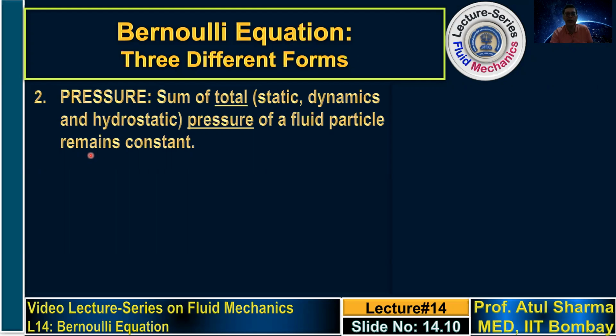So this rho g z that we have in Bernoulli's equation, although it's not strictly correct to call this hydrostatic pressure, this is not the same pressure that we have studied in fluid statics. However, in pressure form, it is called hydrostatic pressure. So these are the three pressures.